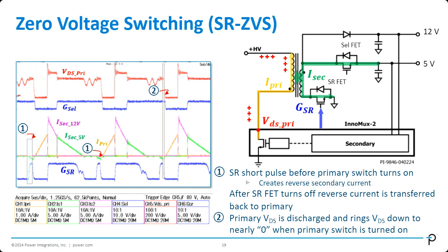Okay. Another thing you might be asking is whether this turn-on time of the SR or the voltage decaying time of the primary VDS node are fixed, and whether you have to set it or do anything. The answer is no, they are not fixed, but you don't have to do anything either. These values, the SR turn-on time and the voltage decaying time, are all adaptive. They are calculated and adjusted continuously to make sure that the SR-ZVS always operates at its optimal condition.